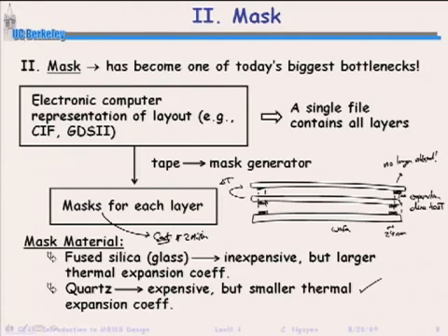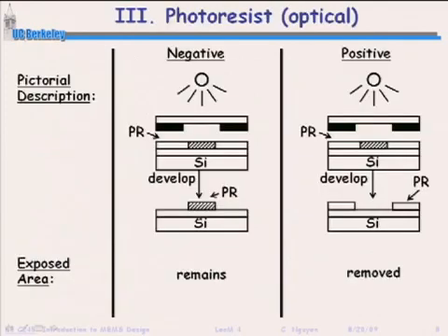And so I mentioned there's two different types of photoresist. There's a negative resist and a positive resist. A negative resist is where the portions of the photoresist that are exposed to light are the portions that stay. If it didn't get exposed to light, it's gone after you do a step called development, which is really an etching step. Okay? Positive resist, exact opposite. If it's exposed to light, it goes. Everything else not exposed stays.